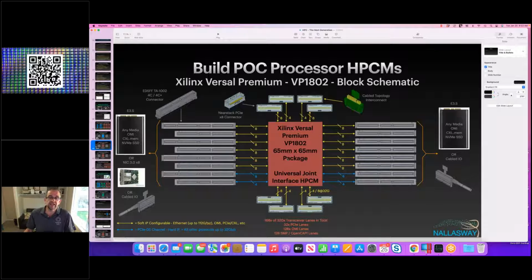This would allow us to connect an NVLink to an SMP, provided you can get the IP from the various vendors. But it is quite an attractive universal joint, and certainly between open standards. That makes it extremely attractive when you're building these heterogeneous systems that otherwise might not like talking to each other. So it's great for that and great for experimentation, as well as all the other acceleration features and architecture fun that the FPGAs bring.